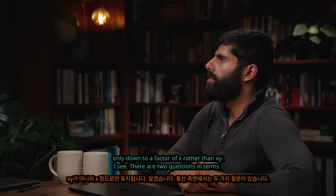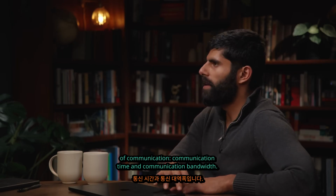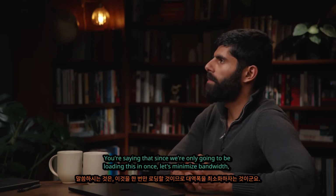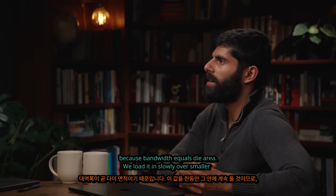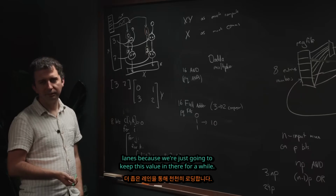I see. Okay. So there's 2 questions in terms of communication. There's communication time, and then there's communication bandwidth. And you're saying, since we're only going to be loading this in once, let's minimize bandwidth. That's right. Because bandwidth equals die area. And let's just load it in slowly over smaller lanes because we're just going to keep this value in there for a while.